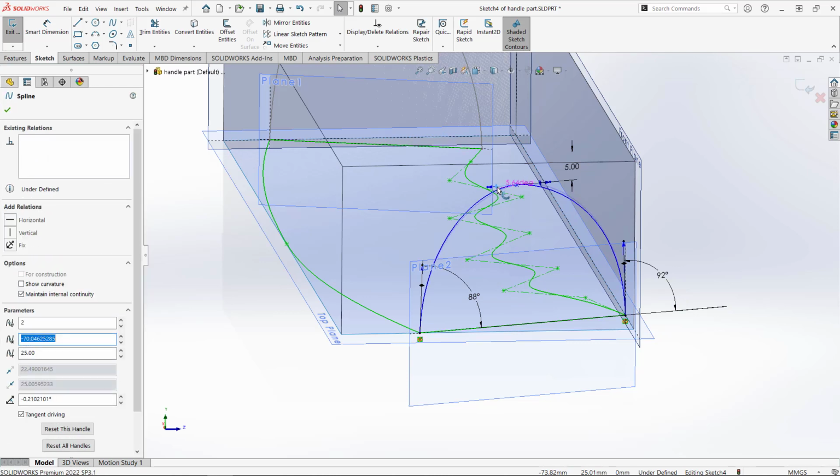I'm going to lock these angular portions of this adjustment handle to be always horizontal over here. So lock them to be always horizontal. That way this point more often than not will describe the highest point of this profile if we lock it to horizontal. It won't always be the case, but it's a nice way of making it more likely that this point will be the highest point of this spline.